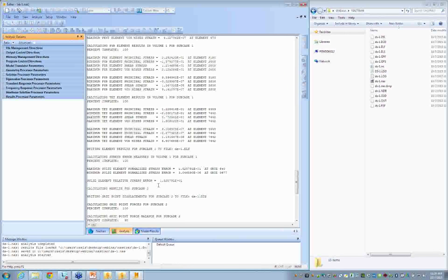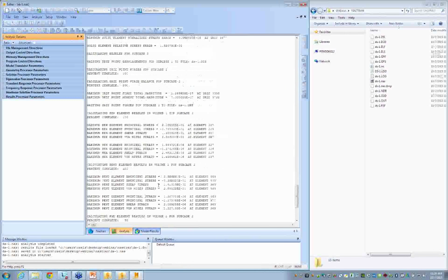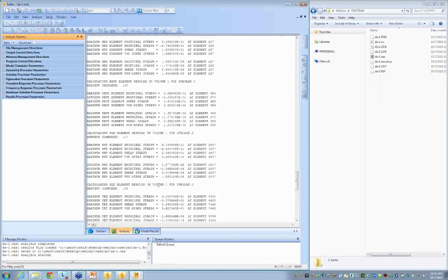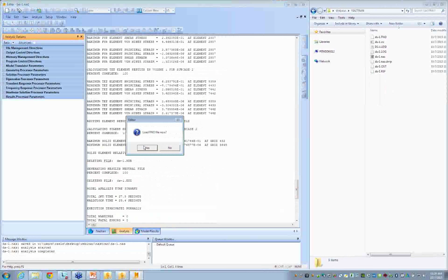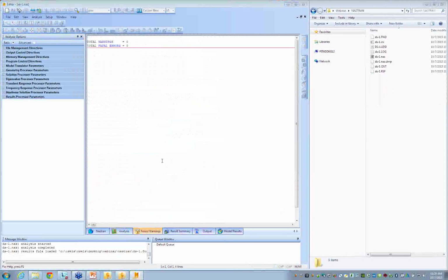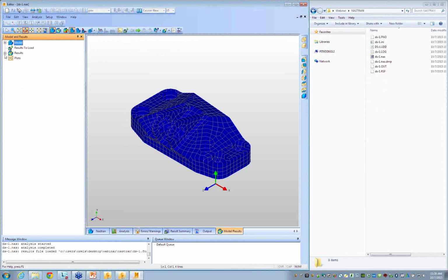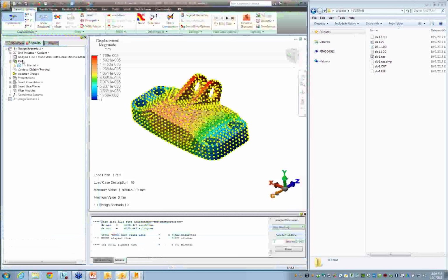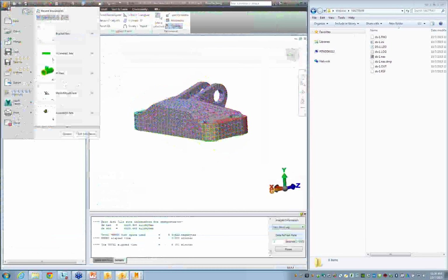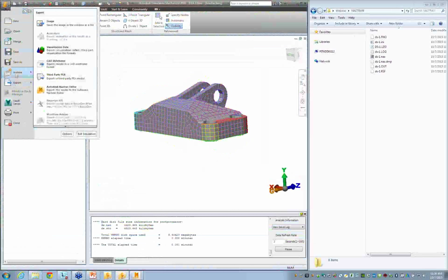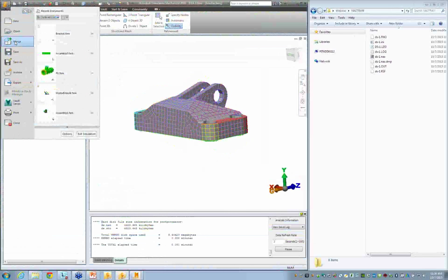All right, so it took me a couple minutes, with explanation as to what I'm doing, to set this up. And I only ran it once, and I have the results. And I'm not really that good at looking at results in the Nastran editor. So what I'll do is I'll go back to Simulation Mechanical, go back to FE Editor, I'll go into here, and instead of exporting, this time I'll do a merge.